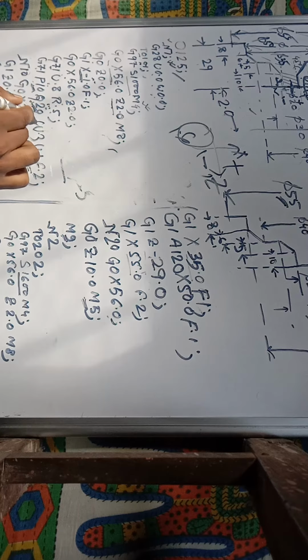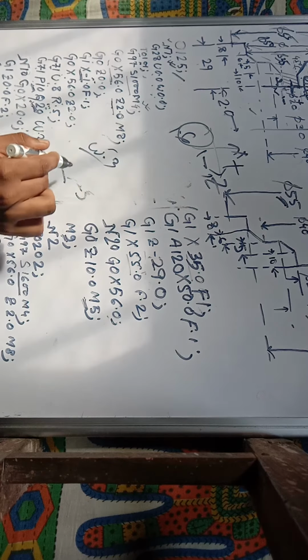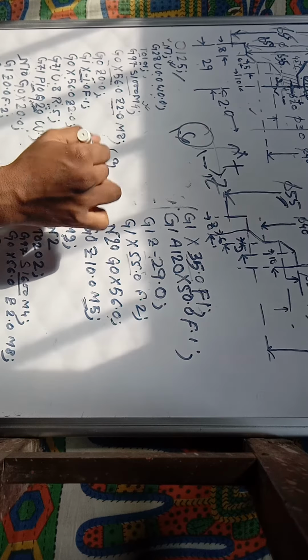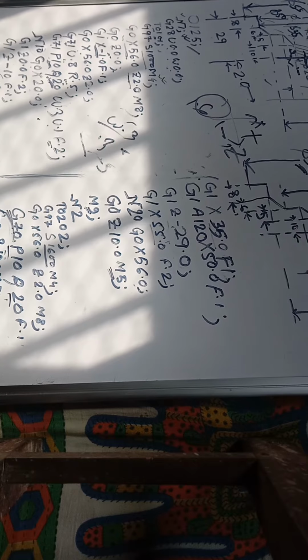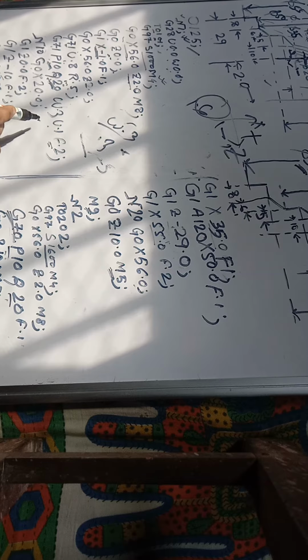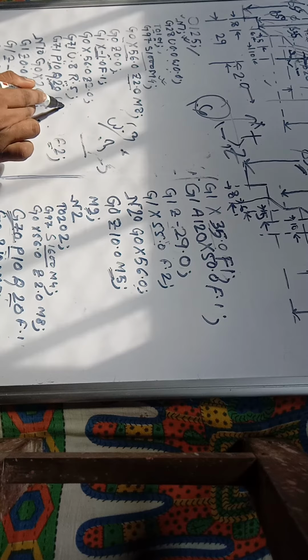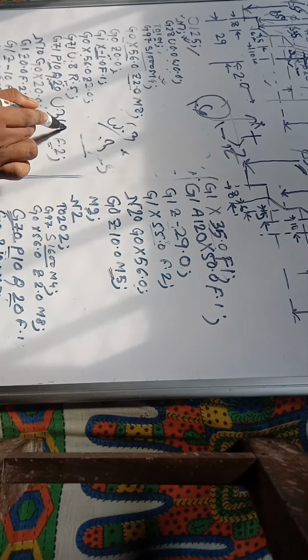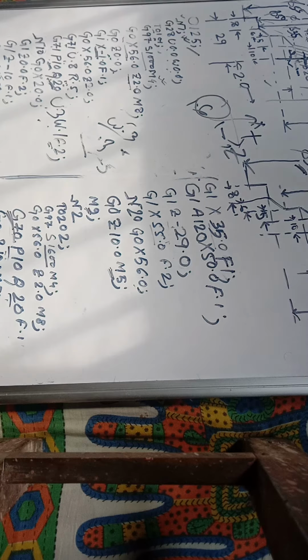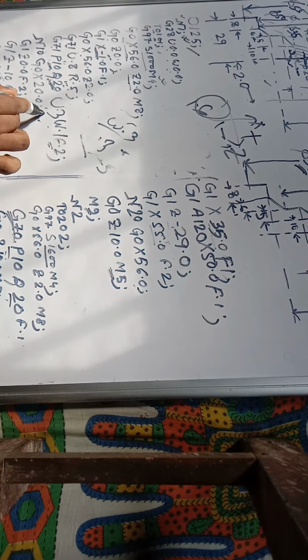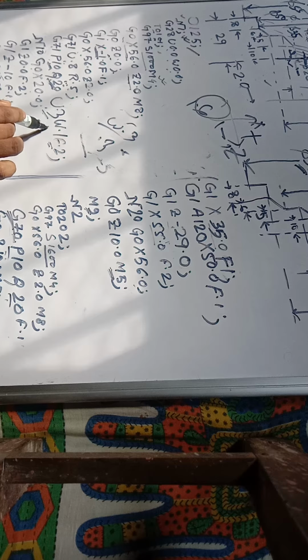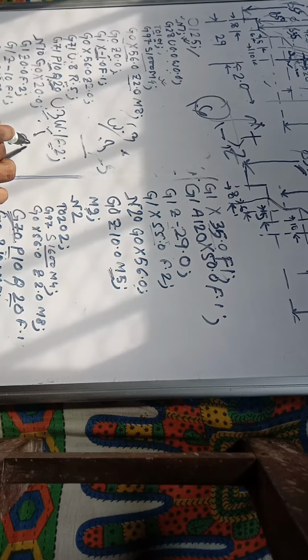W.3, that is material 0.3 is reserved for the finish cycle, which will be called G70 cycle for the finishing path. Sorry, I have given the wrong statement here. That will be U.3 and W.1. U.3 means it is an incremental value, and 0.3 material will be removed in the finish path, and W.1 represents the length. 0.1 will finish at the finishing path of facing.